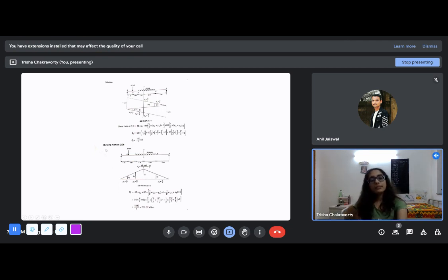So here you see that even if I had extended this uniform distributed load by some zone, suppose I put it from D to B, or I change the magnitude, so long as you have the ILD, you only have to apply some geometrical operations, like take the area under the uniform distributed load, or just take the ordinate at the point load. I can add any number of point loads, any distribution of UDLs, and you just use the ILD. Once you have the ILD, you can apply these simple principles to get the bending moment or shear force, no matter what the loading arrangement is.